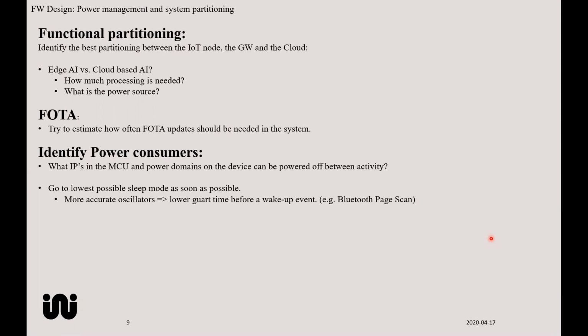In the example that I brought up, using an external RTC rather than an internal RTC, then you might not even have to bother about the low power modes. You just turn everything off. But if you would like to run on the internal RTC, then the lowest possible power mode with RTC wake-up source should be selected.